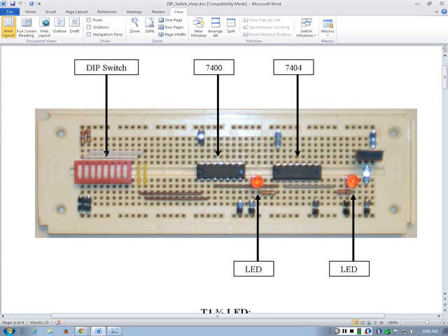And look carefully, the switches are also connected to your ICs. Do you see it? For example, look at switch 1. What we did? We ran a white wire up to this point, and then again we ran a yellow one up to here, because that's how we are connecting. White and yellow are connected, right? Because the point where white ended, yellow started from the same column, because everything in the same column is shorted. So the white one and the yellow one are connected because they're in the same column. Do you see they're in the same column?